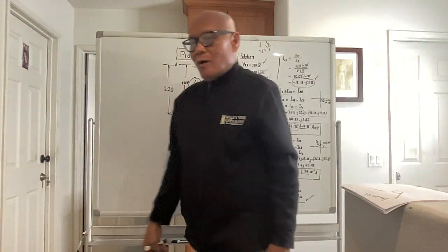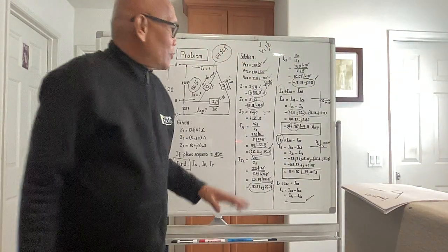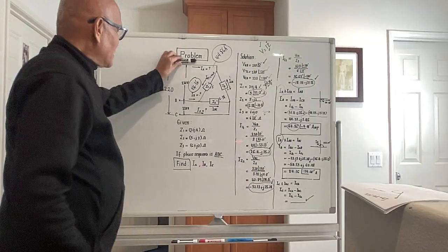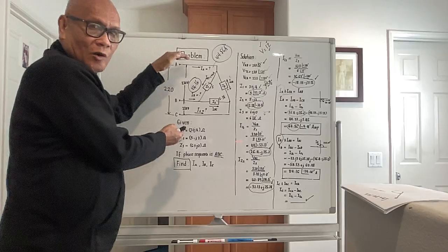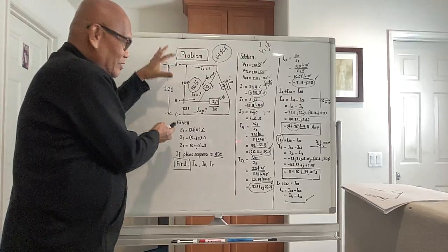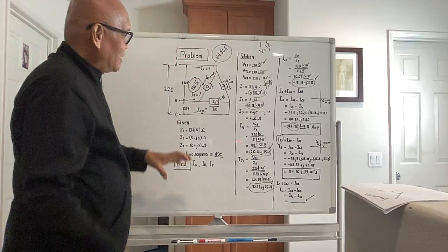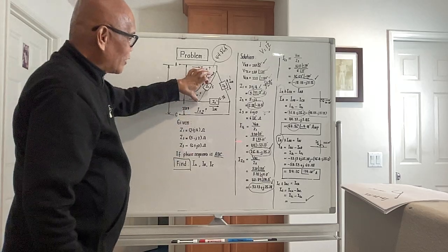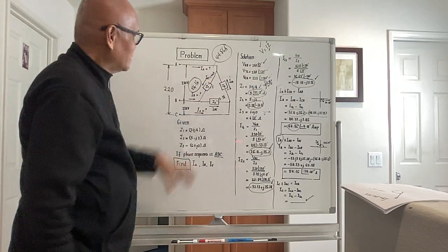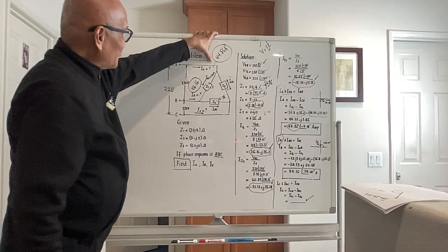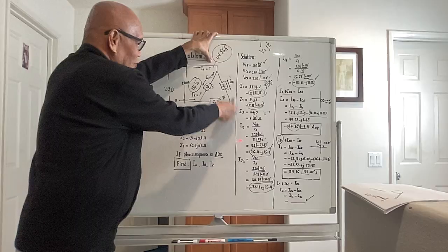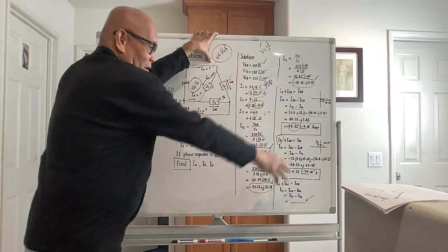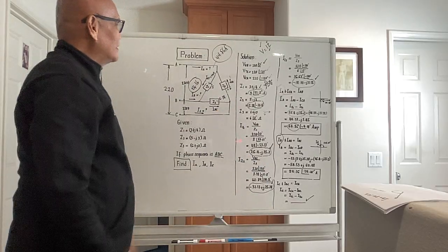That's the way on how to compute for the individual line currents if the input voltage is balanced, but unluckily the load on its phases for a delta-connected load is unbalanced. So this is 44.86, this is 84.16, and this one we do not know yet the value, just continue the operation there.